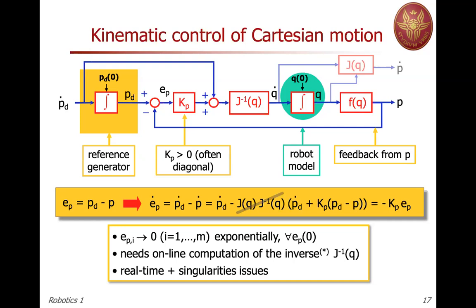Okay, so in order to achieve this type of decoupled behavior, you have to rotate yourself and put yourself on the line or on the tangent, on a frame, which has a tangent direction and a normal direction. So you like to react differently in the two directions, which is like the Cartesian case, but now you have the task rotated in the proper frame. Okay, so this is why frames are so important. So let me go back to the question here.